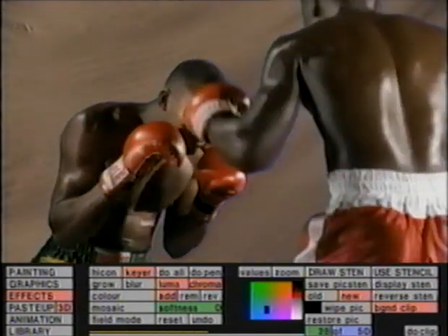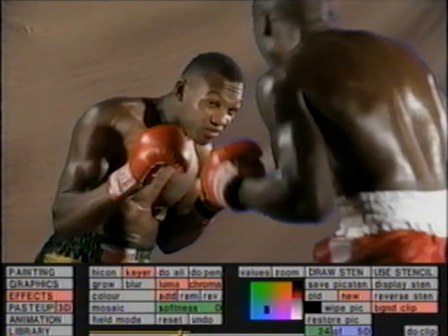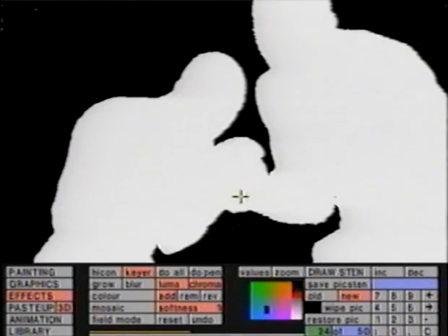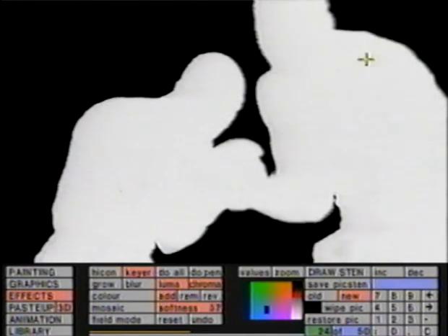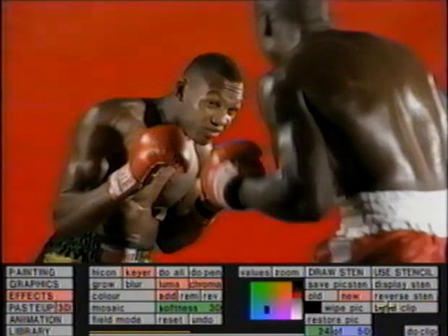Adding softness to the whole key or individually under Values will produce a linear key. The display shows a matte signal while softness is set. At this stage, the key can be processed for the whole clip. The key settings will be applied to each frame of the clip to produce a stencil for each frame, a clip stencil. The key signal produced will probably require further treatment before it's used to separate the foreground.